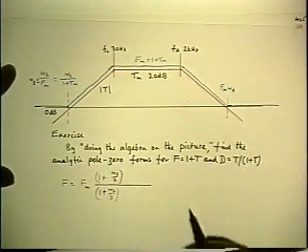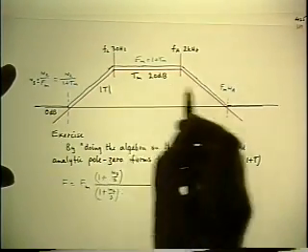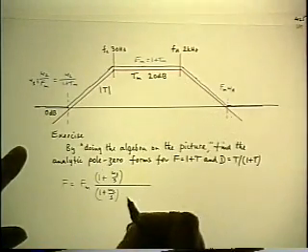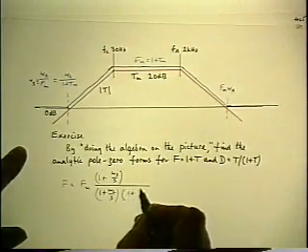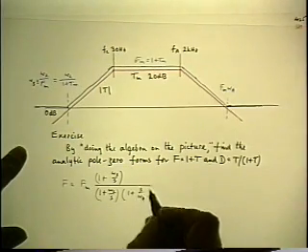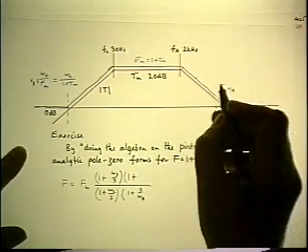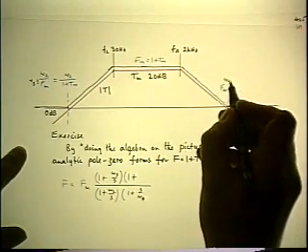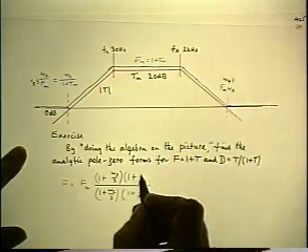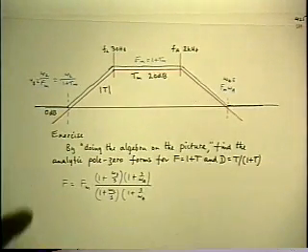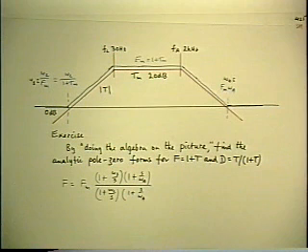That's the inverted 0. And looking up in frequency, this is exactly the same as we had previously. There's a normal pole at omega a, 1 plus s over omega a, followed by a normal 0 at this frequency, and I'll define that as an omega 4. So that's a normal 0. So that's the factored pole zero format.